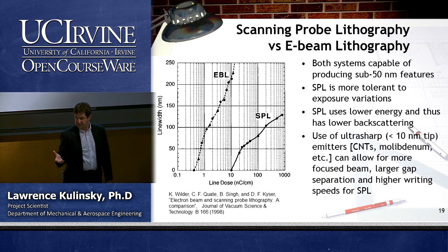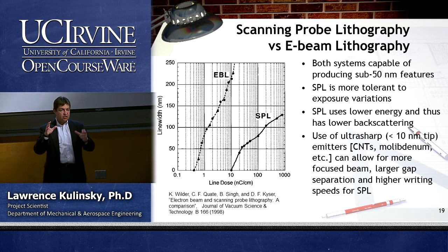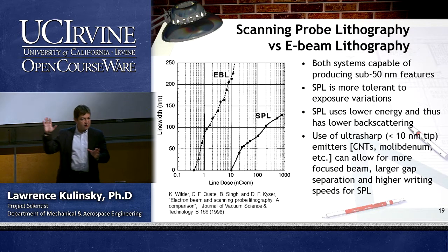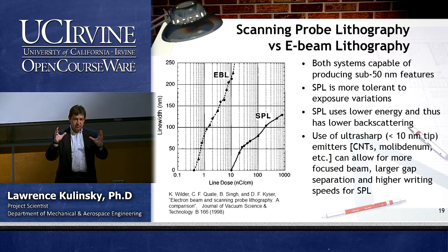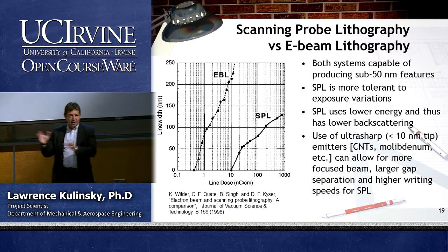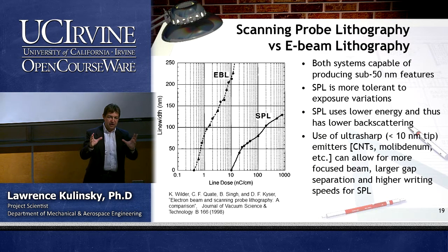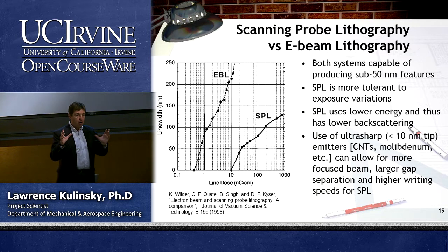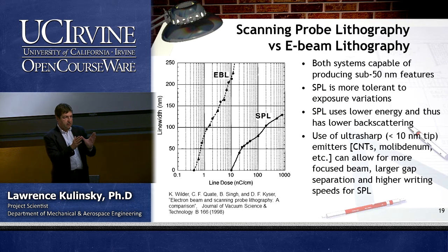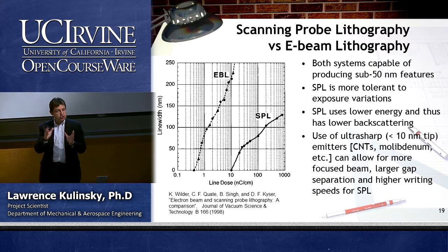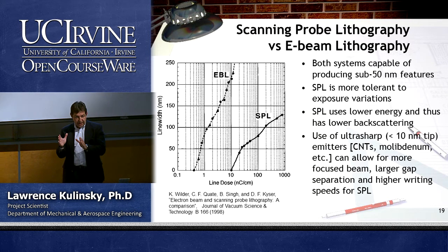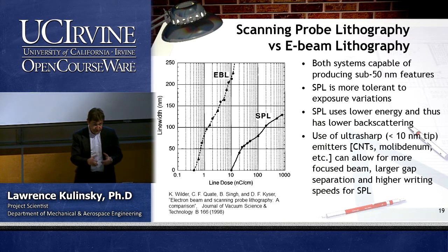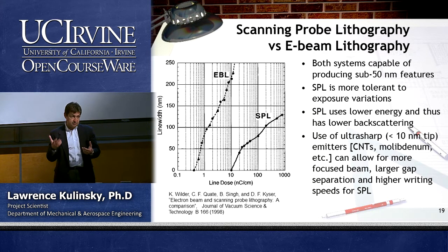So have you covered regular lithography? Yes? Okay. Remember that in your lithography, in I think the second slide, we talked about the Rayleigh or Abbe's formula, the diffraction limit. Your resolution improves if you have shorter wavelengths. So if you use electrons and ions, it is more efficient, with better resolution than just visible light.